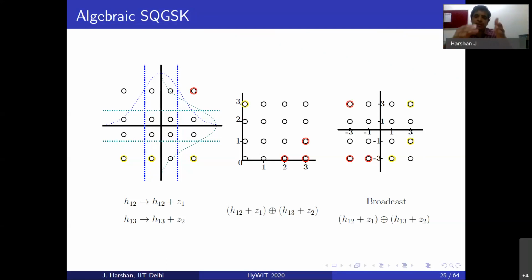And that means it's asymmetric. It's going to have large mass points in the center and minor mass points on the side, and that is not really congenial for key generation because the underlying randomness itself is not uniform. So at the phase of quantization, we don't want to use a QAM constellation. Instead, we would like to design a constellation which looks something like this, and that forcefully ensures that the quantized samples are uniformly distributed. And this can be done if we have the knowledge of the distribution.